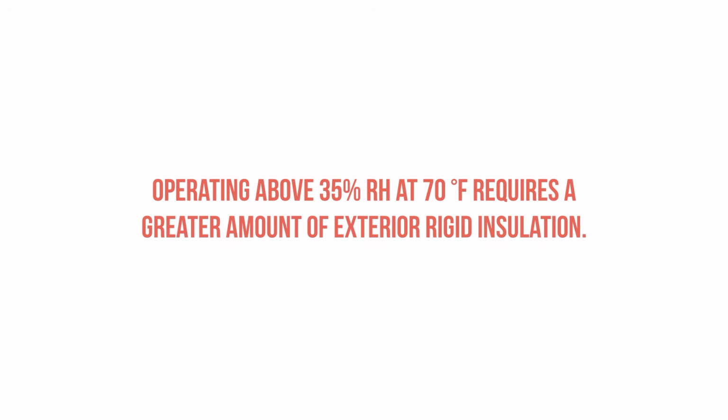If you operate at a higher interior relative humidity, you need a greater ratio of outboard insulation to prevent condensation, since it's much easier for interior humid air to find a cold condensing surface.